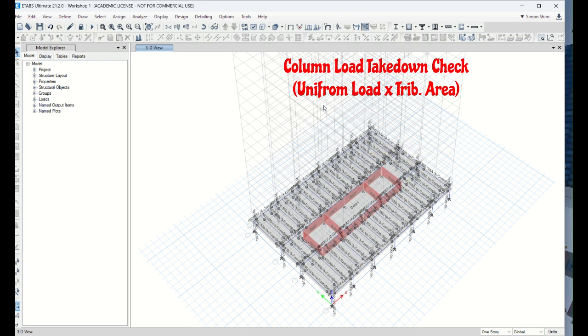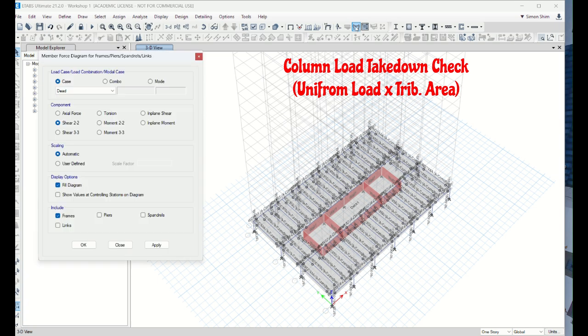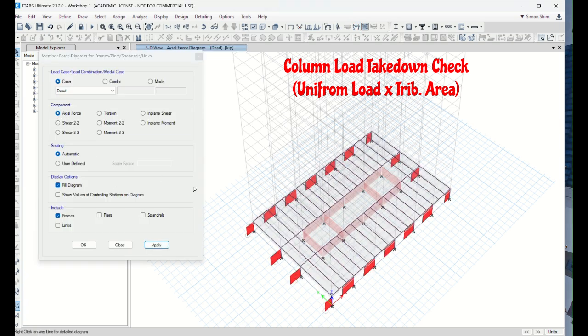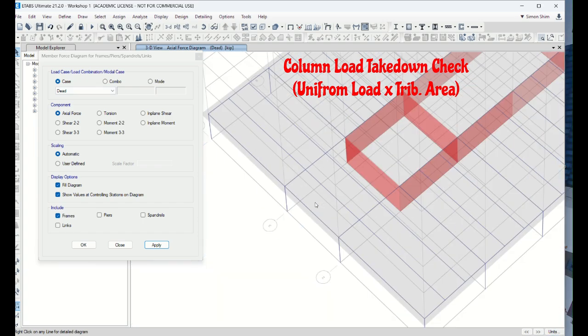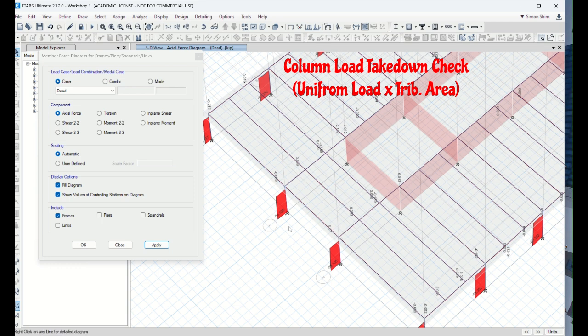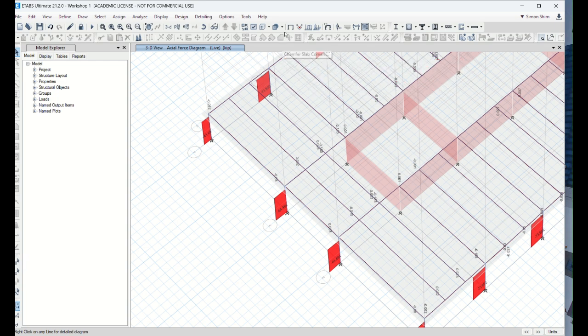Now, once we finish it, we can double check the color actual force diagram, right? This is based upon gravity area. We already studied it a few times. See that due to the self-weight, you see 55 kips. You should be able to calculate this by hand. If it's simple, with 100 PSF live load, 100 PSF times gravity area, you can get this column reaction. All right, so I think everybody should finish up to here.